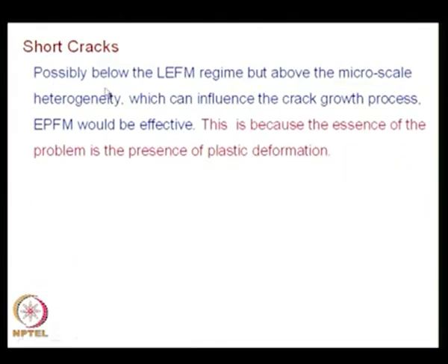What we could do is possibly below the LEFM regime, but above the micro scale heterogeneity which can influence the crack growth process, EPFM would be effective. This is because the essence of the problem is the presence of plastic deformation.